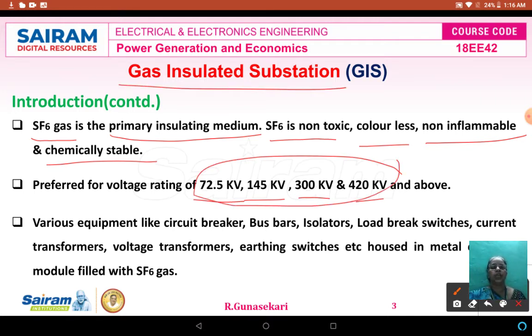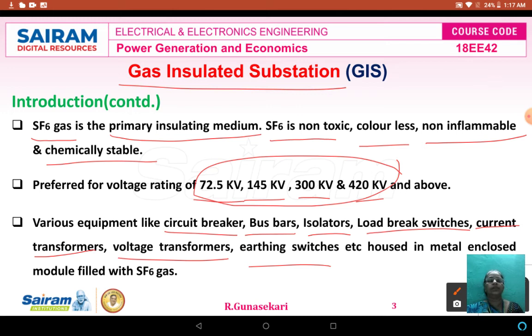The equipment used in the gas insulated substation includes circuit breaker, bus bar, isolator, load break switches, current transformers, voltage transformers or potential transformers, earthing switches, etc. All of these are housed in a metal enclosed module filled with SF6 gas. This is very important.